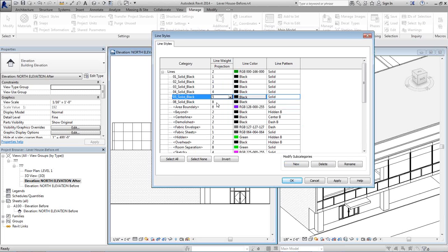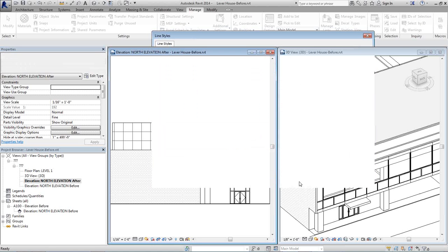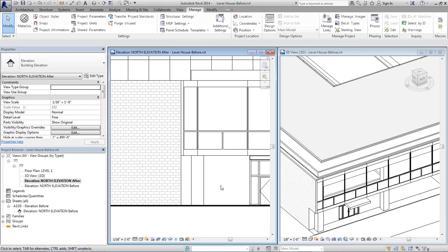The thing that's the closest to the viewer here is this canopy. Ultimately I want to show you 2 techniques for creating this depth, and this is the first one. The first one is really using detail lines. So literally, you start with a Revit model, with all these modeled elements, but essentially draft over that model using lines of a certain thickness.